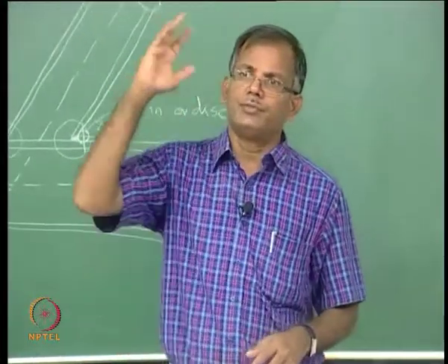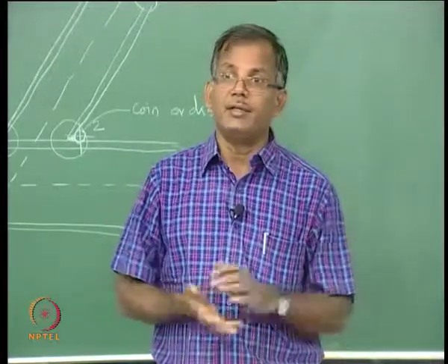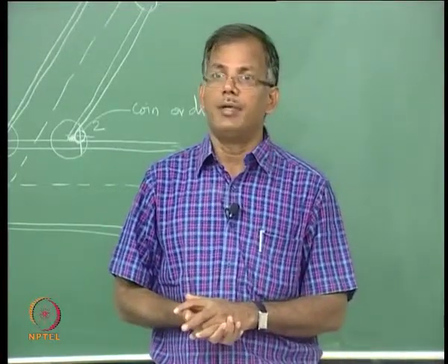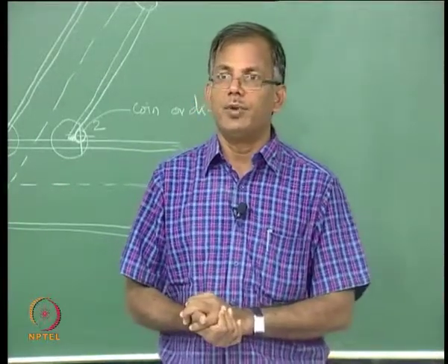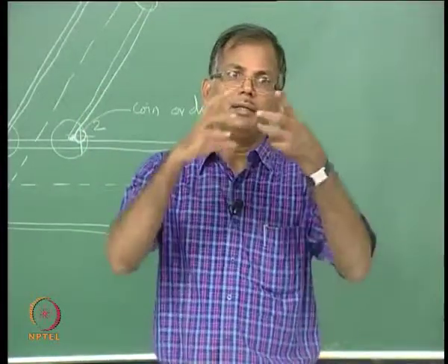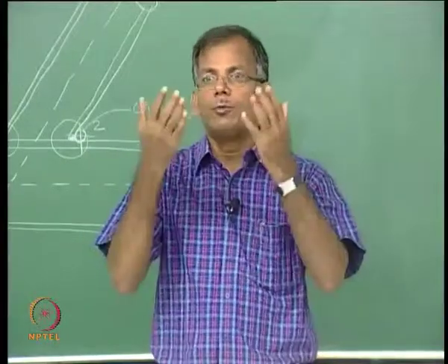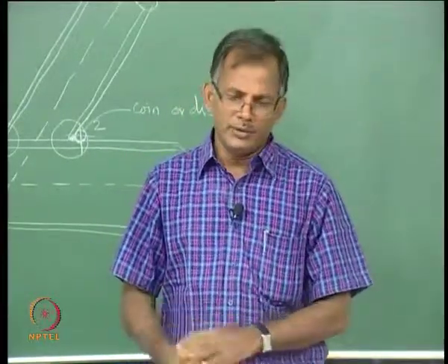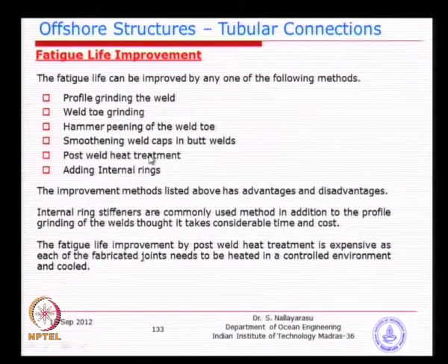Some of the joints fabricated in Gulf of Mexico for our big jackets, 450 meter jacket, they had a larger problem of weld cracks even during welding itself. So, what they did was actually heated the joints after welding and then cooled down at a controlled rate. So, basically post weld heat treatment is nothing but trying to relax the weld after welding.